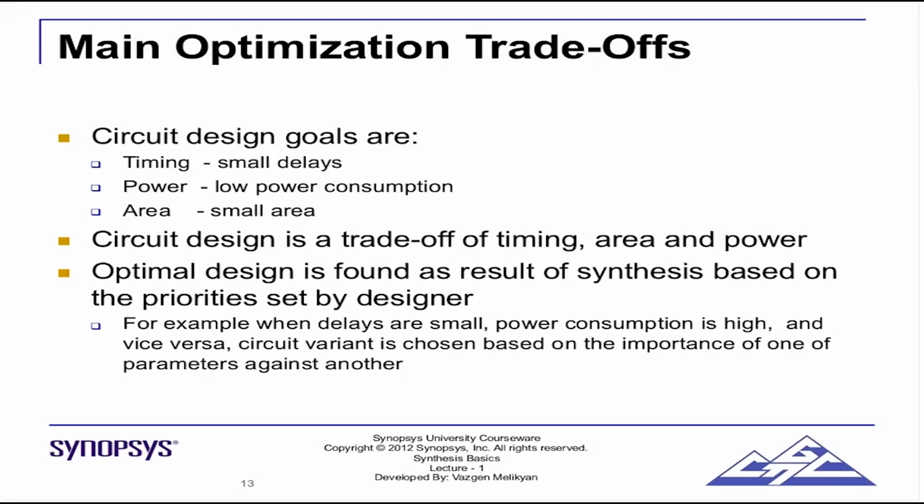So let's say there is a CPU, an 8-bit CPU or 8-bit MIPS microprocessor design. Now let's say I synthesize it for a 400 MHz target, and then again synthesize it for a 600 MHz target. What do you think will have more area?